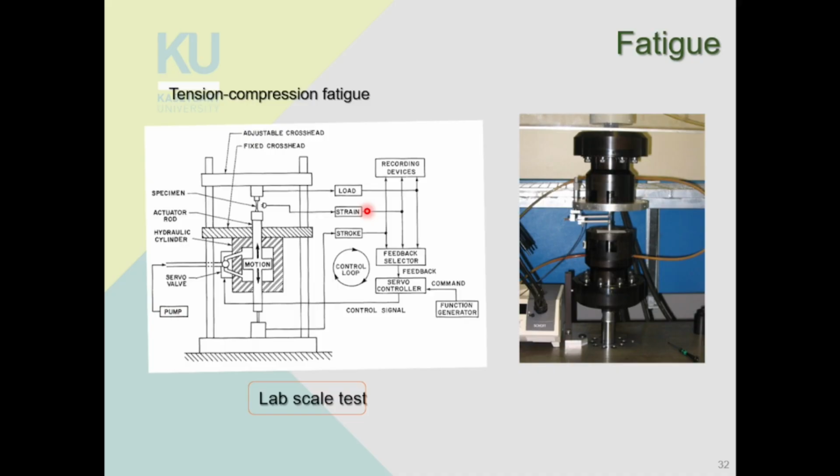Another type of fatigue testing in the lab scale is called tension compression fatigue or push pull, right? So instead of bending the specimen and rotating it, we are pulling and pushing the specimen. Right? So we're loading the specimen in the vertical position, and then we're pulling it, pushing it, pulling it, pushing it, really, really quickly, up to about 20,000 hertz, right? We're doing that really, really quickly. So we're applying stress, measuring the strain, and we are doing that 20,000 times a minute, right?